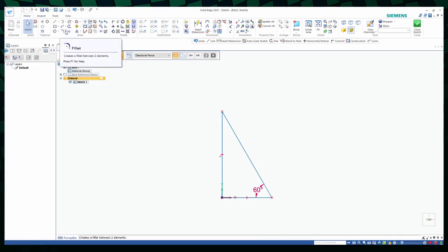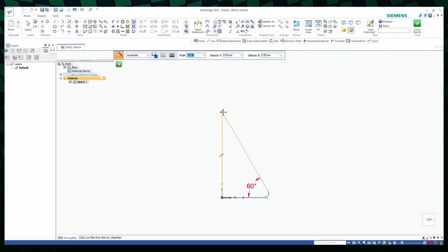Now onto another feature. You can click on this option to add a fillet to a certain corner. Type in 10 on the radius and press enter. You can also add a chamfer. For example, in this top corner, you can set different setbacks to the different lines or select a different angle, but in this case I've just clicked randomly, as this is just for showing purposes.